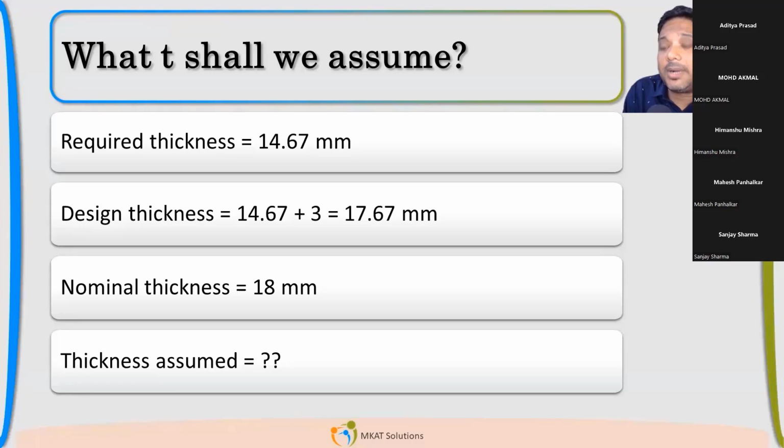But if I am able to qualify that 15 mm, which is the end of the vessel life, and the pressure vessel is able to sustain the external pressure, I'm good enough. Getting it, guys? Say yes in the chat box if you got it.